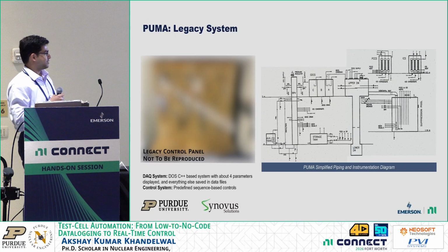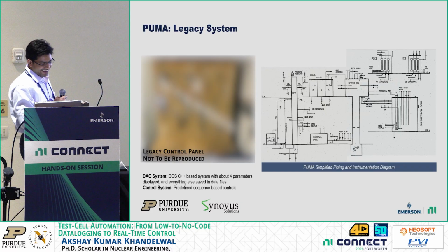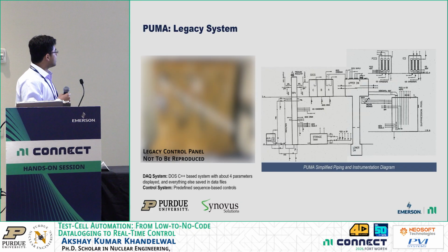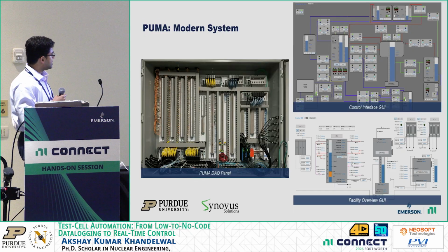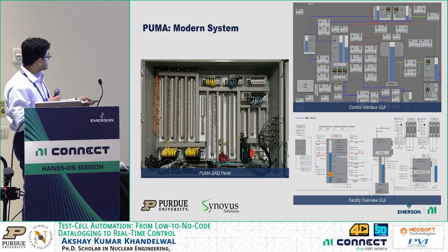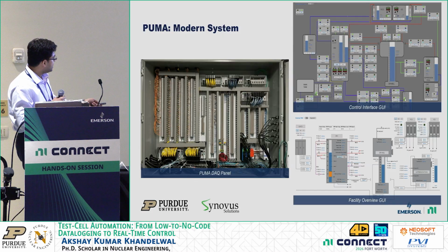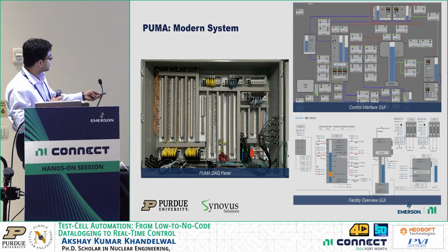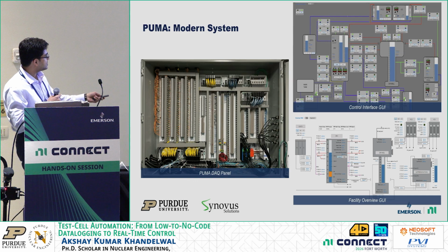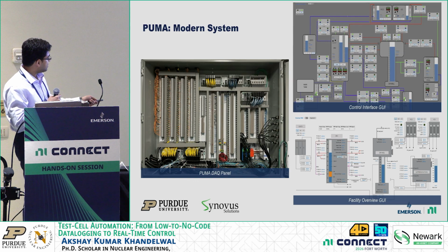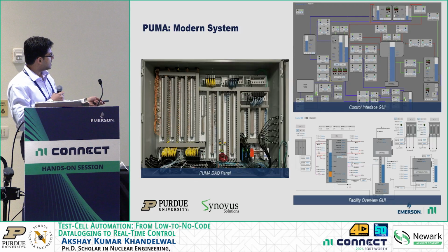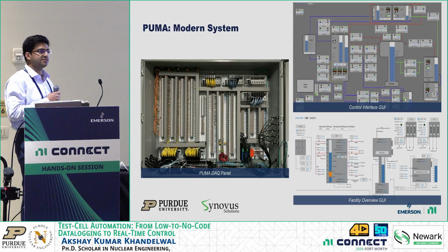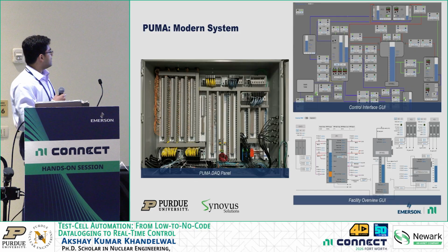And then our control system was basically this. This is our control system. So now what we have built using CDAC and CRIO is we have all of the temperature measurements being taken on this side, all of our current measurements being taken on this side, and this is our control side. So you can see we have CDAC, and that's our CRIO. All of this is connected to Ethernet lines using 2 switches, so it also provides us with data redundancy.